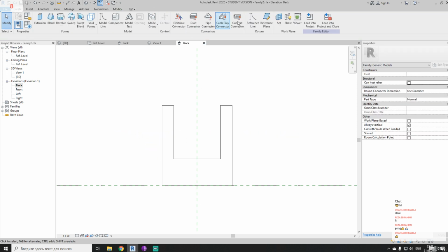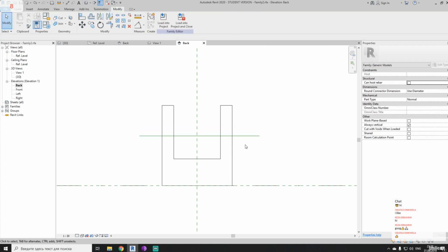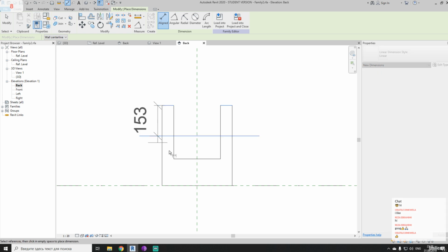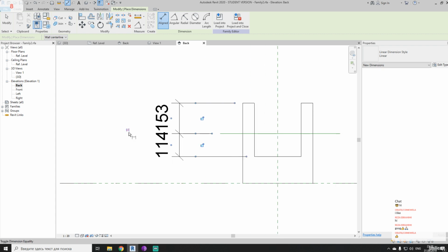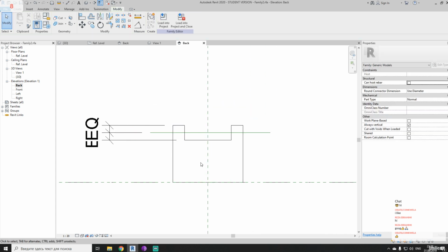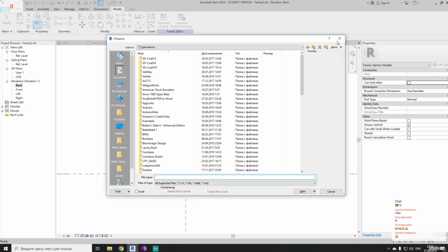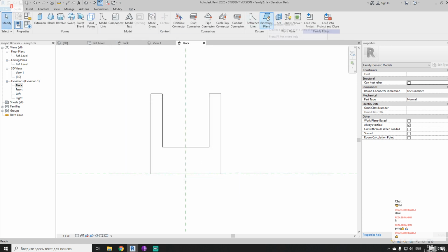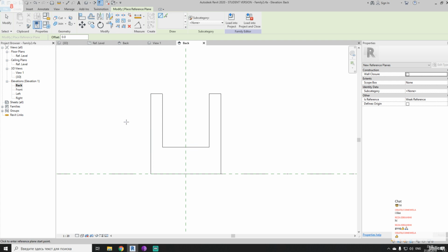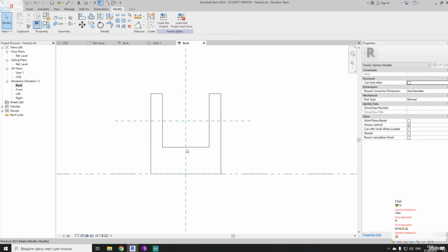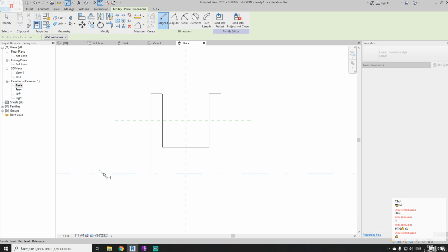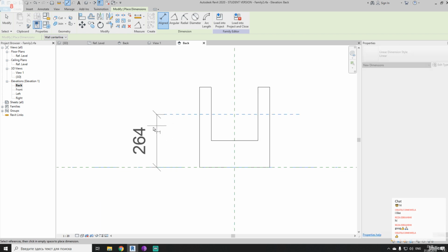It's not working. But we have also, I mean the reference plane, but we have also the reference line. With reference line, we will sometimes get the same problems, because we're connecting our model with the line, so sometimes it's not working. Why am I saying sometimes? Because we get a result like this. It's terrible. It should not be like that. So what I'm going to do actually, I will use my reference plane again, like this, and I will use dimension line. And I will connect from my zero, from this ground point, to that point.